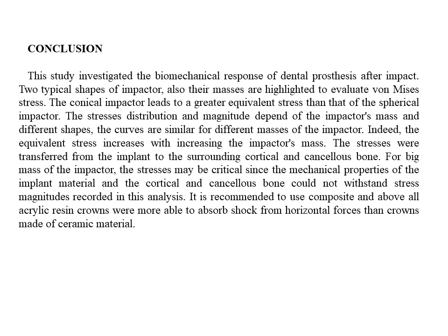The curves are clear for different masses of the impactor. Indeed, the equivalent stress increases with increasing impactor's mass, and the stresses were transferred from the implant to the surrounding cortical and cancellous bone. For a big mass of the impactor, the stress may be critical since the mechanical properties of the implant material and the cortical and cancellous bone could not withstand stress magnitudes recorded in this analysis.